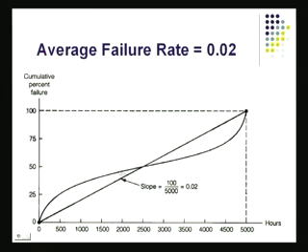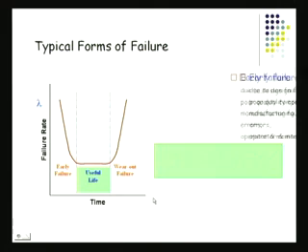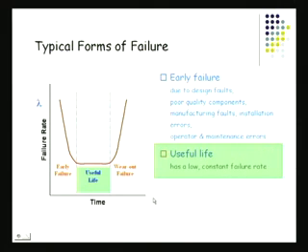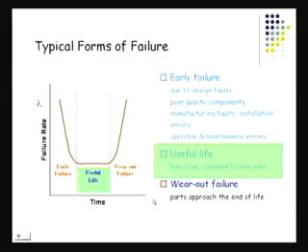And in between, you'd actually enjoy a failure rate that's going to be smaller than the overall average. The same thing can be said again if you look at the bathtub curve. There is the early failure period phase, then there is the useful life, then of course the wear out failure. These are the three phases in almost any product.